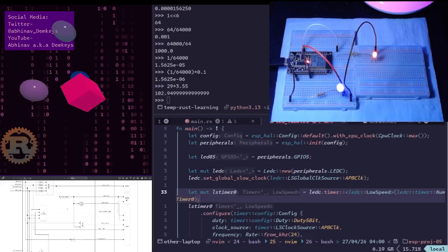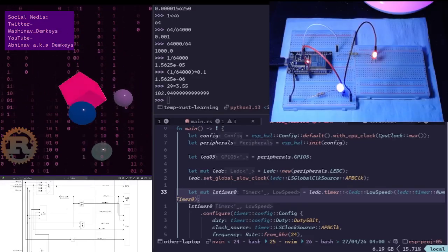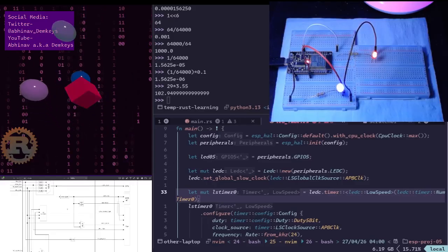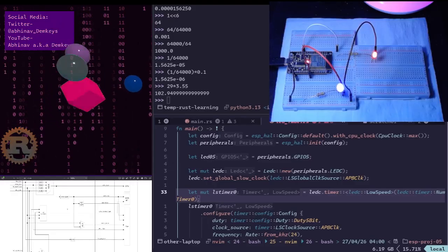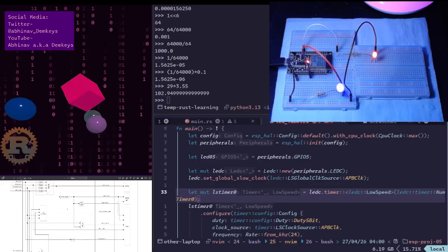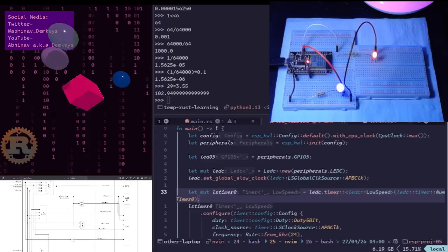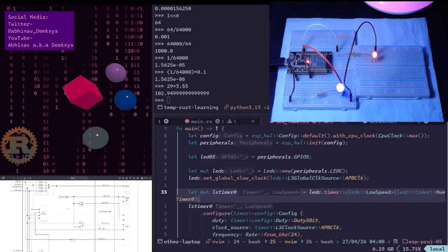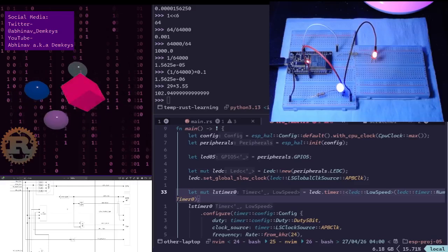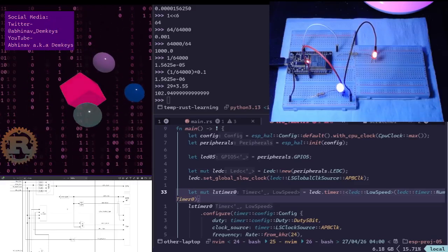Then we have stage two. Stage two is the timer configuration. That's the clock source. Even though you told the peripheral to use the APB clock, the individual timer needs to know what it's looking for. Purpose: in Rust, this is largely for validation and math. The configure method needs to calculate the divider. Divider equals F input divided by F target to hit your requested 24 kilohertz.